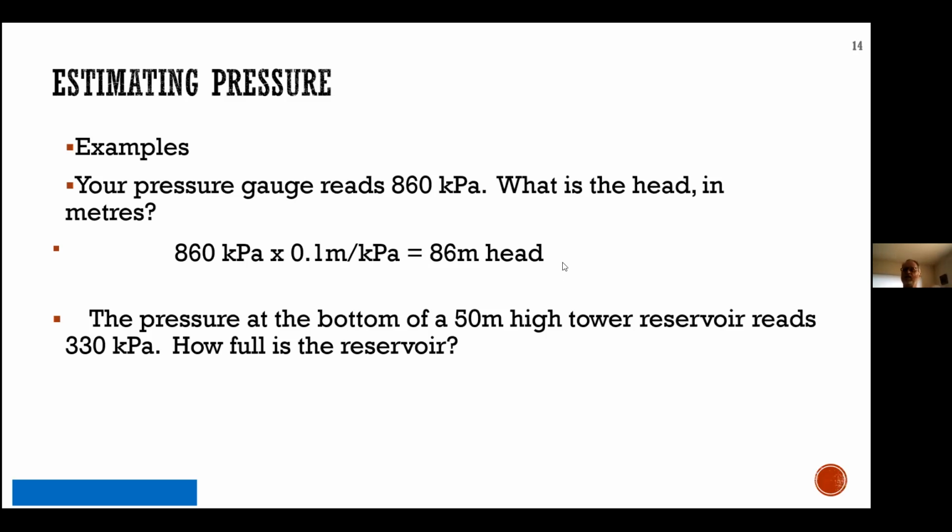So that means that at the gauge, there is this invisible column, but it's there. It would be the same as someone takes clear glass tube and connects it all up vertically, 86 meters, and then asks you to hold the bottom of it. There will be 860 kPa acting on every aspect of your hand, right? That you won't be able to hold it.